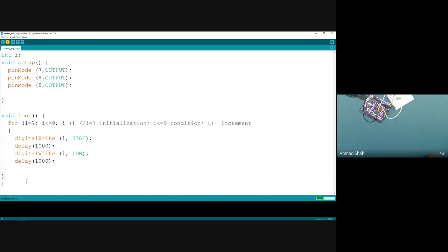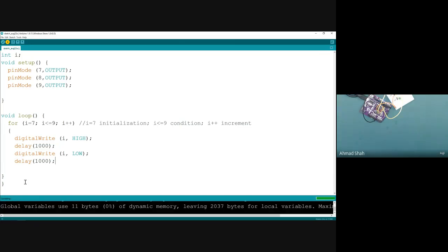So why can't I upload it to my Arduino board? Have you done the configuration step? Click Tools, click Port, and click COM. So what does it show you? What does it tell you? What is the error, or can you not detect the port? What is the error? Can you share your screen, if you want to? Or it says it was not declared in this scope.